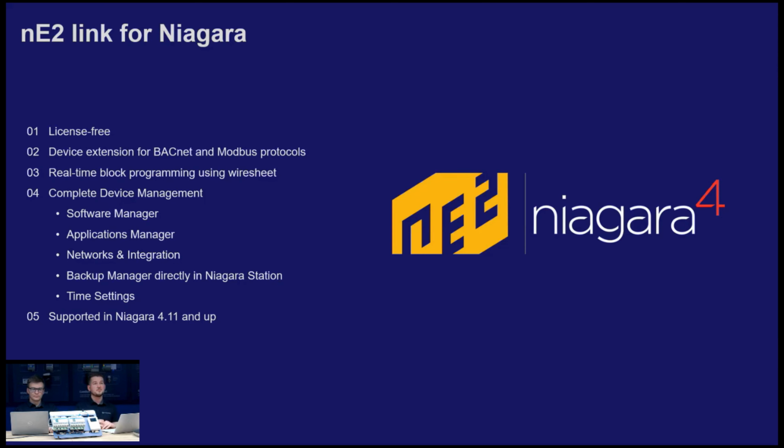We prepared also the complete device management, so you have access to the software manager. You can install the latest updates, like the 1.7 we are mentioning. It's going to be available as an update process. You'll have access to the applications manager, to all networks for the integration. So you can use the local IO network just to create the local application on the controller. Or you can expand it with the control point panels, touch point panels, or our IO modules, or the FCUs, or any RS-485 devices or IP devices over BACnet and Modbus.